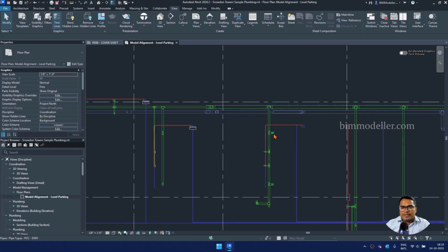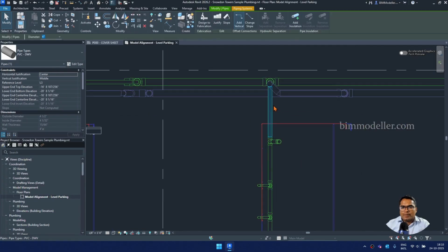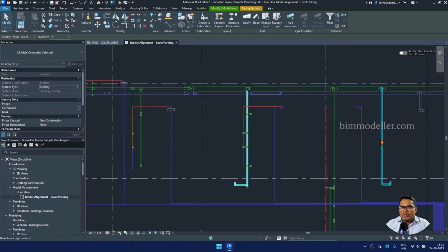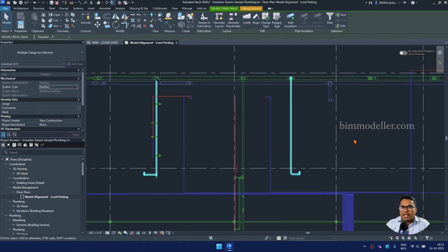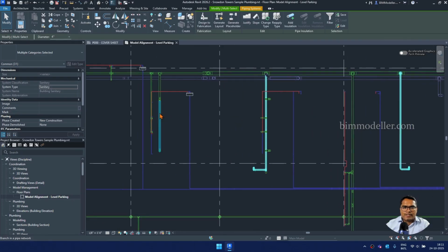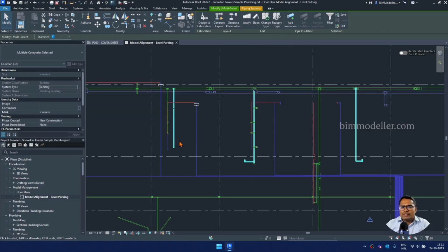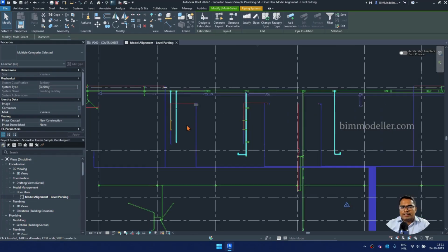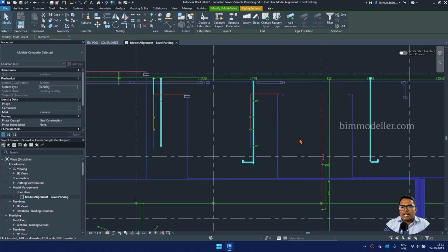When you select the elements, for example, all these elements, if I am selecting them, or maybe an entire segment of these elements, say from here. In the previous tutorial we talked about how to select these full stretches like this, and I'm going to select this stretch. I'm holding the Control key and I'm going to select this stretch, and maybe like this. So now I have to say that these segments are in zone 1. These are the sanitary pipes, the waste pipes that I have selected.